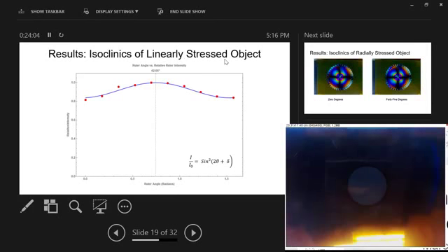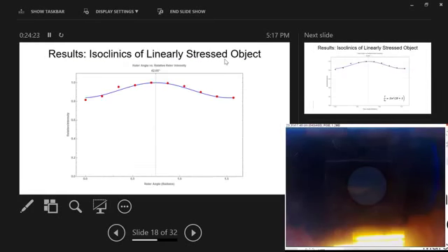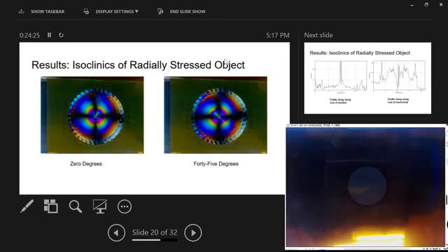It's whether it's in line with the analyzer polarizer. But based on images that we'd seen in textbooks, the fringe pattern that we got out of our ruler seems to correspond to a stress that's along the short width of the ruler. So not this direction, but in this direction. So that was the first experiment.